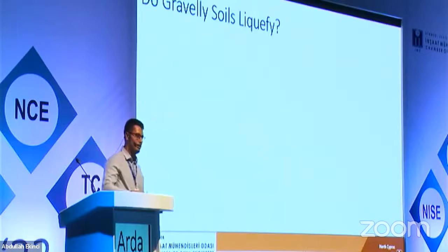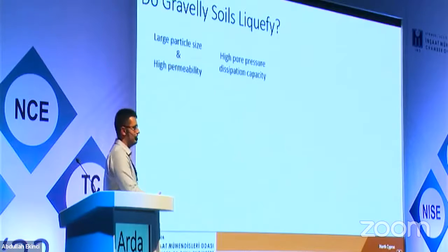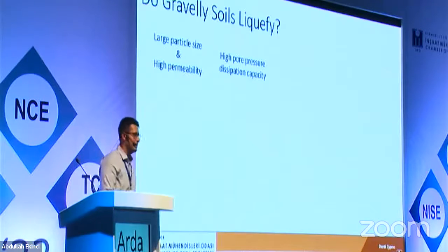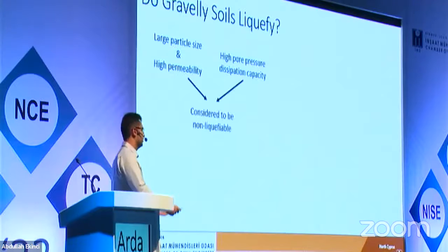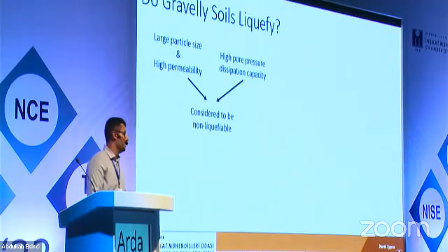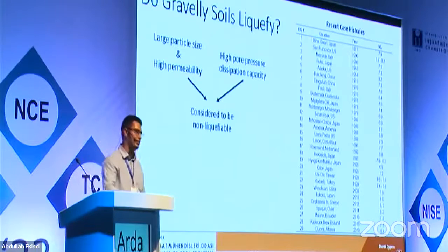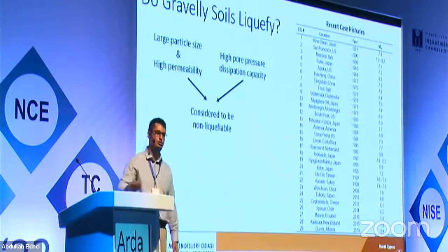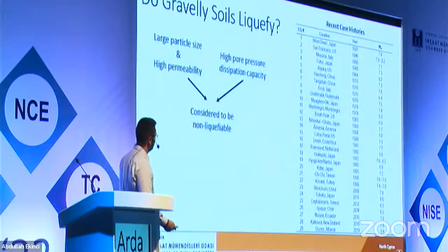So do gravelly soils really liquefy? Why do we think they don't liquefy? We have large particle size, high permeability, and due to this, high pore pressure dissipation capacity. So they are considered to be non-liquefiable. However, we have some cases, actually a lot of cases, showing gravelly soil liquefaction, and from these cases we understand that they have some probability to liquefy.